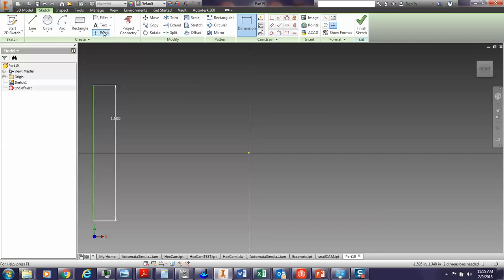But I'm going to put points down so I can create my arc. So I'm going to put a couple points. I'm going to make sure those points are laid out so they are on the same vertical axis. Then I can start my arc. I'm going to use the center point arc. So I'm going to use this as a center point. This is my larger one. Remember, it's going to go past 180, something like that. My smaller one is going to be like this.